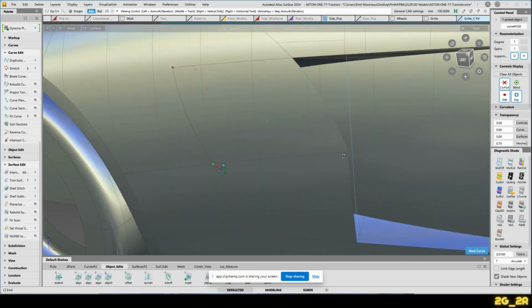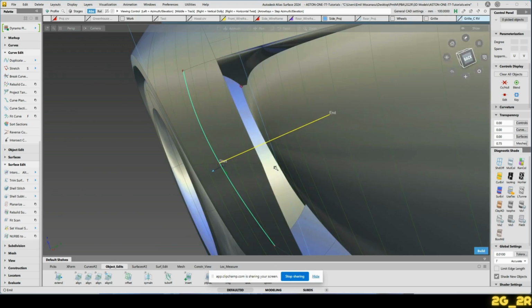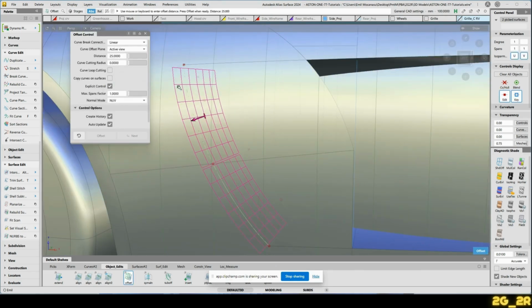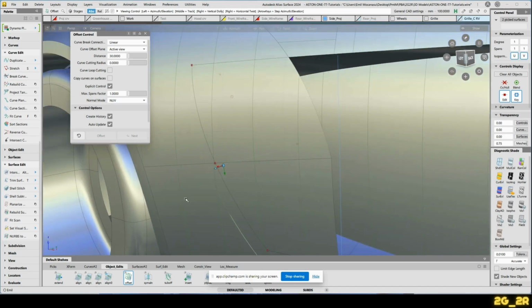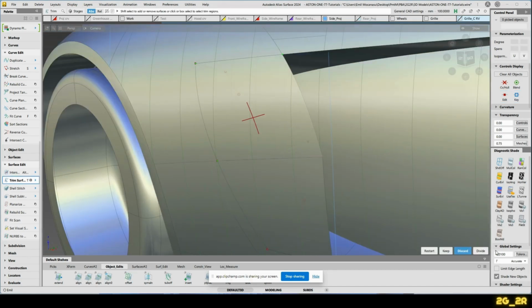And build a big surface off of that. So I'll build profile of those two frame surface on that line there. And I'll offset that by, let's say, 30 to have some kind of a pocket looking thing in there.